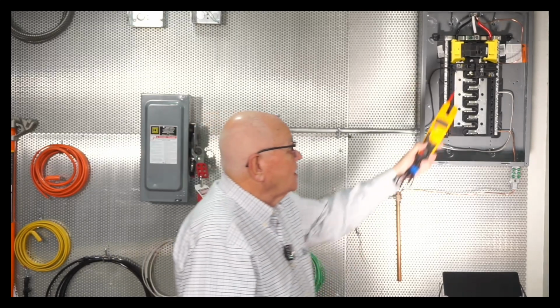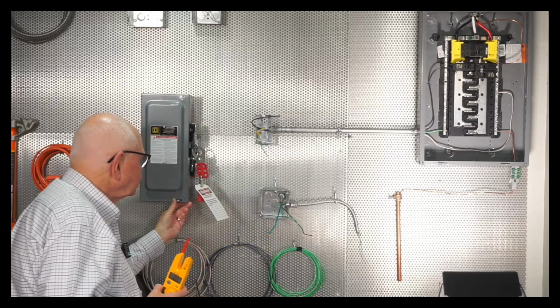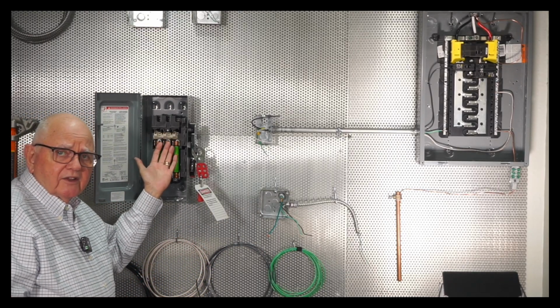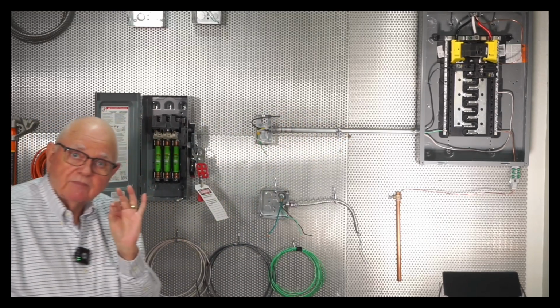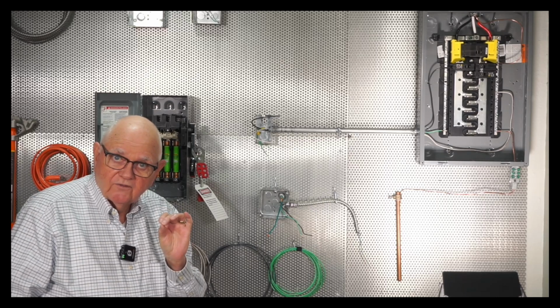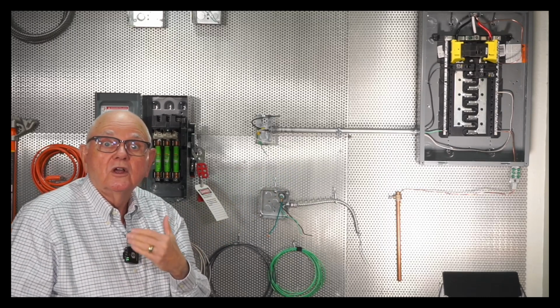The size of the branch circuit is whatever my overcurrent device is designed to protect. This is a 20 amp branch circuit, 20 amp circuit breaker, so it's a 20 amp branch circuit. Here's another example. This would be for a motor over here. Let's say I were supplying a motor with these fuses. Now the fuses and the circuit breaker, remember, supply short circuit and ground fault protection. Short circuit and ground fault protection supplied by fuses and circuit breakers, and that's covered in Article 240.